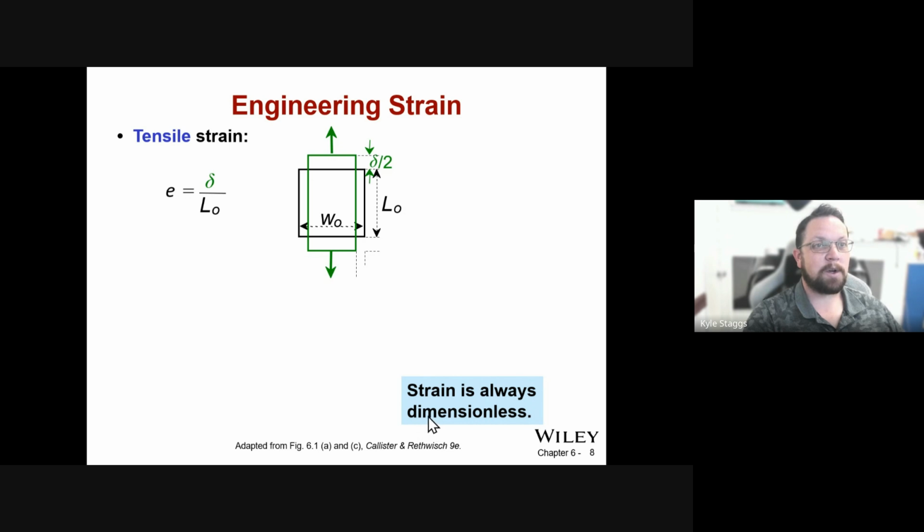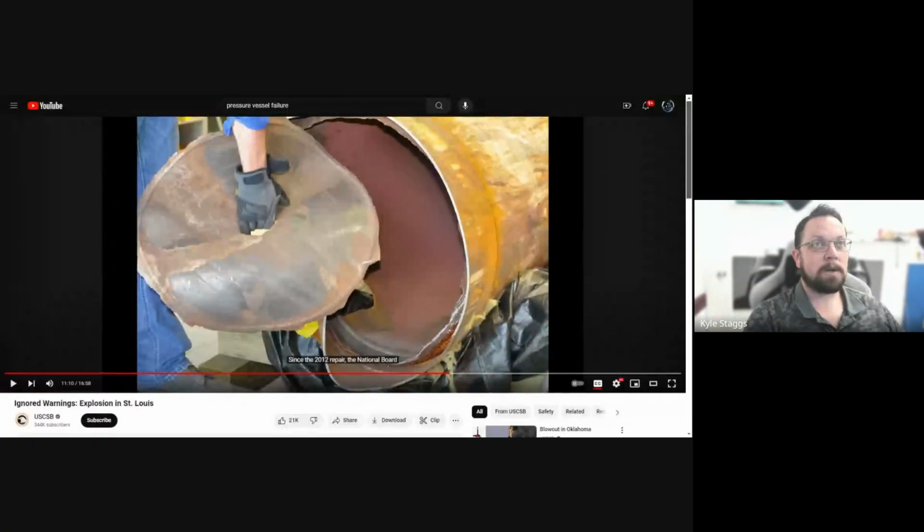The heat affected zone is what is immediately adjacent to the weld. And if we look back at that for just a minute, where it failed specifically is literally right at the outside edge of this weld. This is typically how these are going to fail.